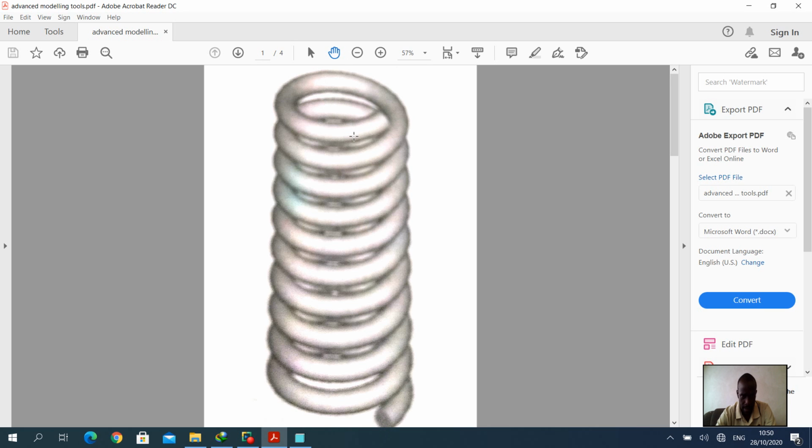And the next important detail that defines this helical nature will be the pitch, which is the distance between two coils, and it must be constant right throughout. This is the pitch, a constant pitch of 10 millimeters, which must be constant right throughout the length of the spring, which we are going to assume as 20 millimeters.